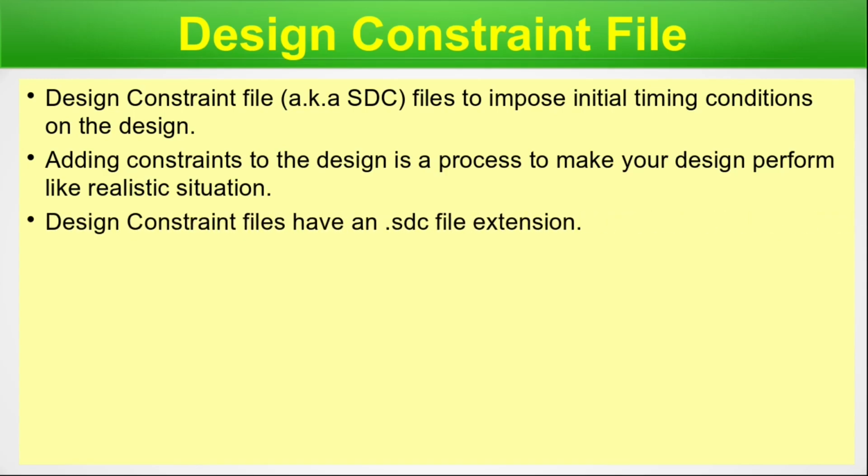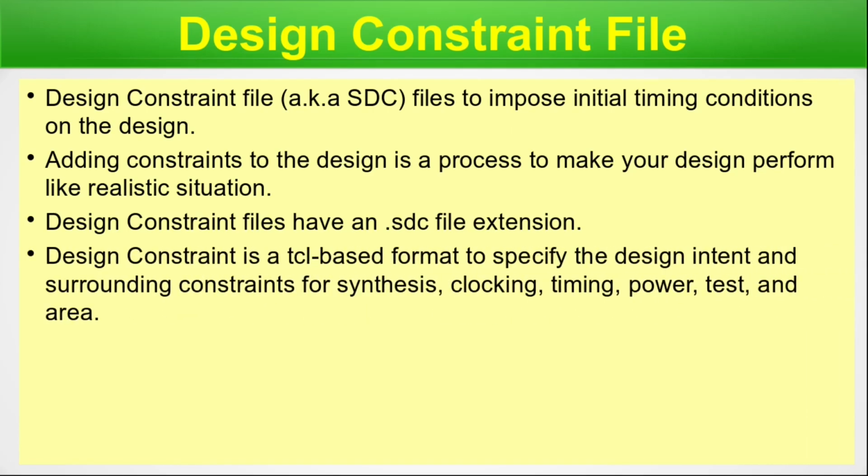Design Constraint Files have an .sdc file extension. Design constraints are in a Tcl-based format to specify the design intent and the surrounding constraints for synthesis, clocking, timing, power, test, and area. This is a very important point. All the design constraint commands are nothing but Tcl procedures. In the Tcl series, I have already explained how Tcl works for VLSI. In case you have not watched that episode, I'll provide the link in the description.